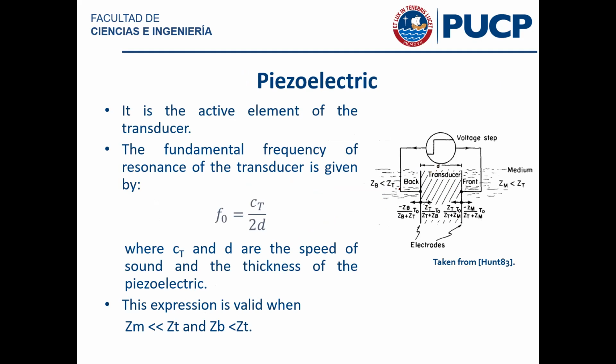And then again, just like we described before, you apply electric currents or a voltage in between the back and the front of the piezoelectric material, and you apply an alternating voltage, and you will have a vibration of the device. And this will actually give you an output that resonates at this particular resonance frequency, which is shown in here.